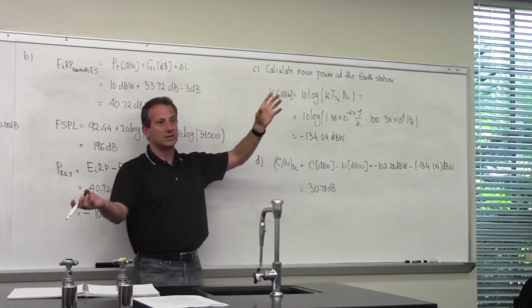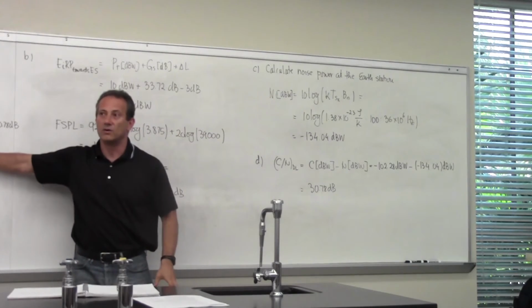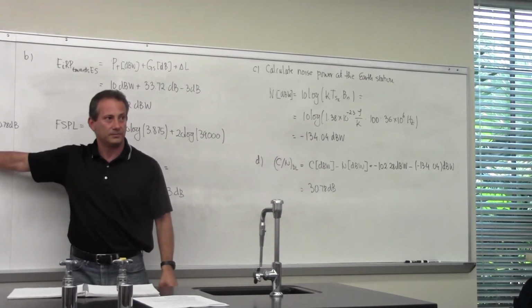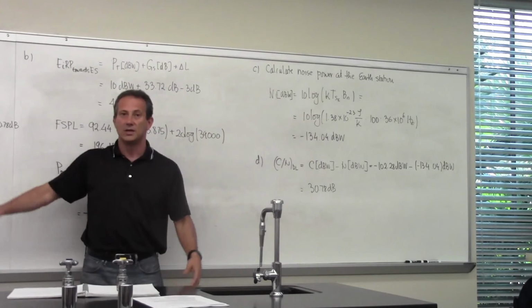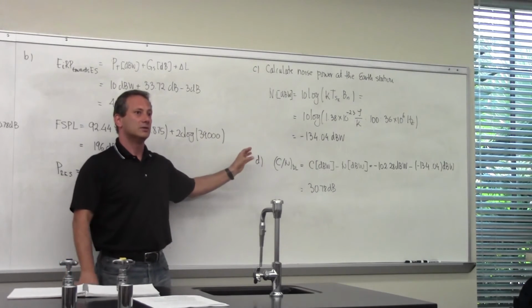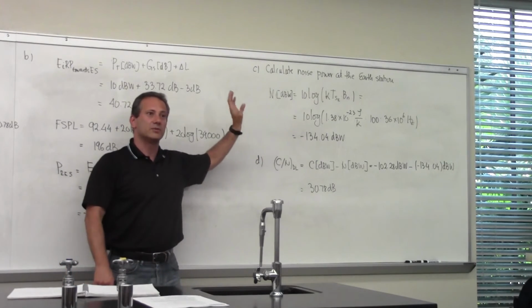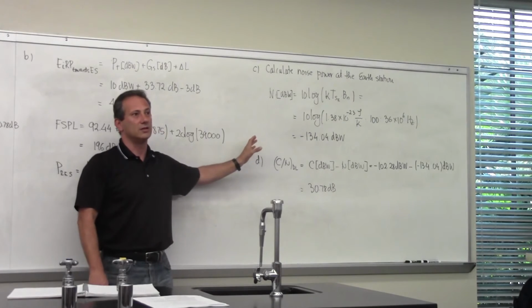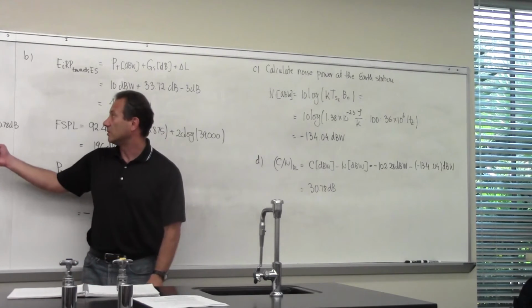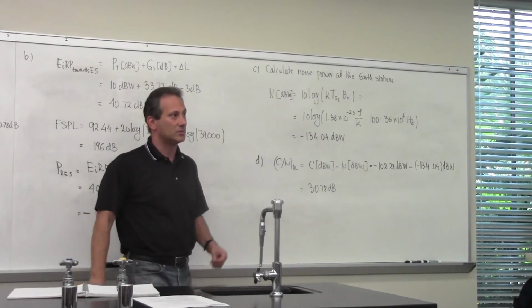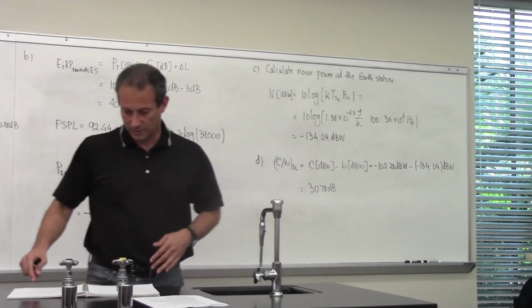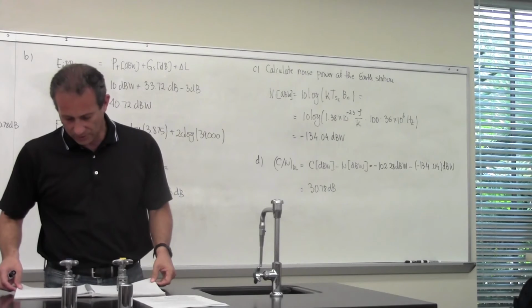The noise that comes from the noise figure of the LNA at the earth station and from the radiation from outer space is 1,000 times smaller than the signal and noise combined that comes from the satellite. So its contribution is negligible. So really, this 26 is predominantly what determines the overall signal to noise ratio.